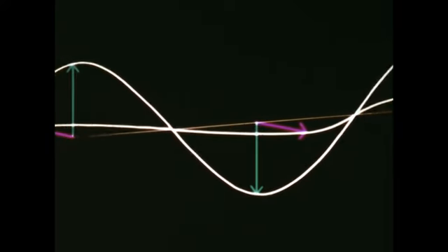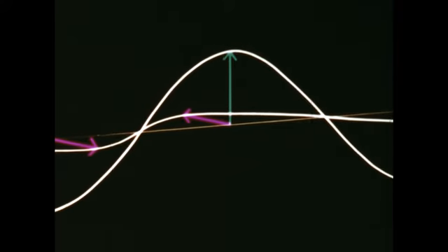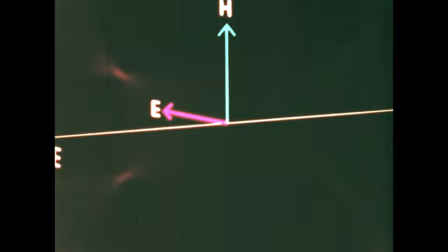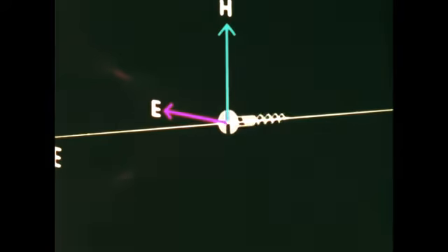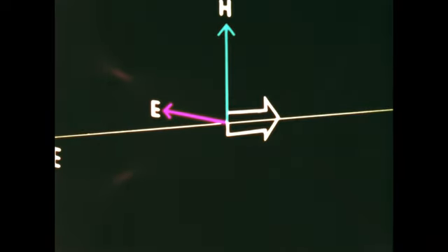The direction in which the E and the H wave pattern propagates is determined by a simple rule. To apply this rule, we use any two vectors. Imagine a corkscrew action. If we turn from the E vector to the H vector by the shortest distance, the screw has advanced in the direction of propagation. This is known as Poynting's vector rule.